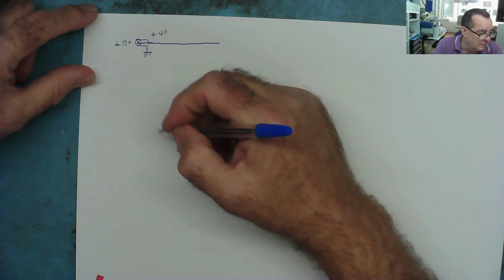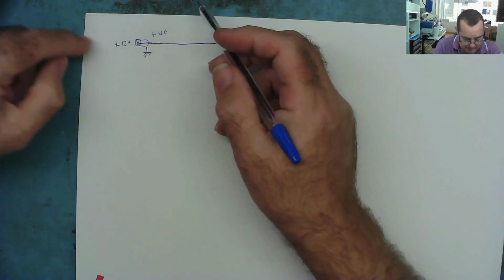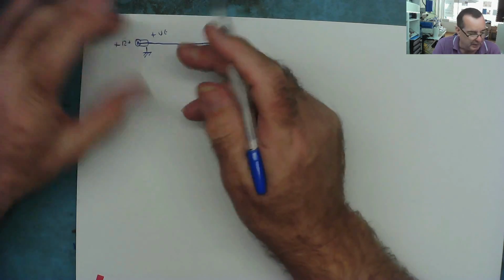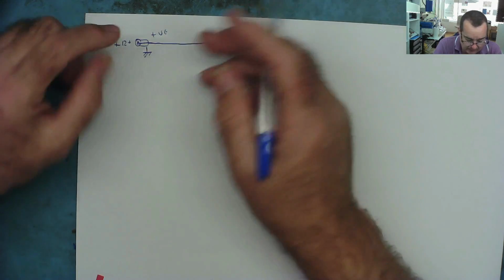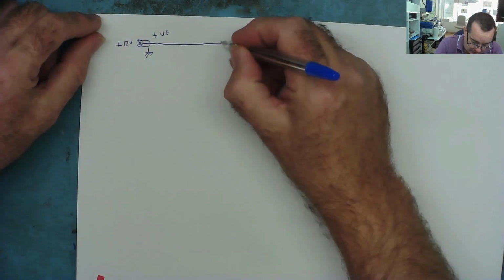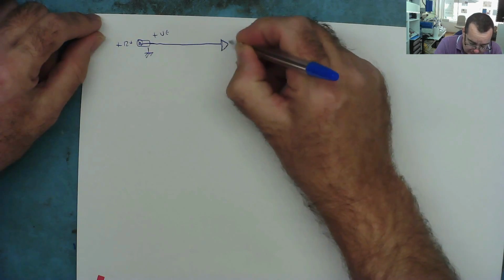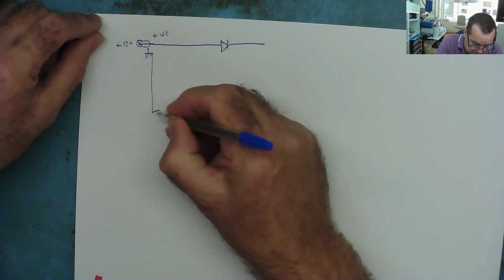Now it's quite possible to have a power supply that's wired the other way around with a negative here, so there is a possibility of plugging the power connector in the wrong way round. For this type and similar situations where you could connect something the wrong way round, quite often they'll just put a rectifier diode in here, and then this goes to ground.